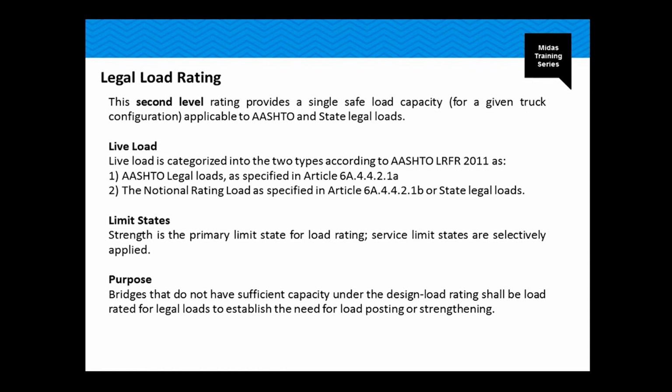Then for the limit states, the strength limit state is primary for the load rating, and the service limit states are selectively applied. The purpose of this second level rating is that bridges that do not have sufficient capacity under the design load rating shall be load rated for legal loads to establish the need for a load posting or strengthening. So the second level is used for load posting and strengthening.